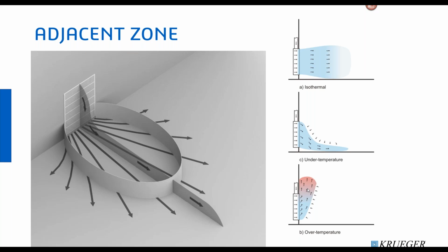Displacement is still perfectly suitable for many applications on the interior zones where primarily you're going to be concerned with cooling only. That example I mentioned earlier, where we utilize some of these in our training room, that training room is in the interior zone of a building. And so we actually don't have to worry about supplying heat to it throughout most of the year. So really that room, the training room, is supplied by displacement units alone, and it's only supplied in cooling mode.